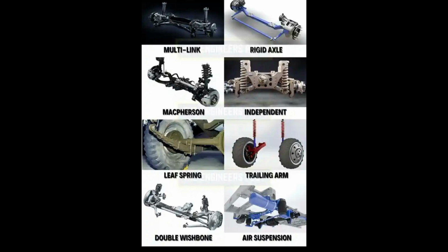Multi-link is a type of suspension that has quality grip, and with this suspension, controlling the car becomes easier. The multi-link suspension also has many variations. If this suspension is damaged, then the replacement process takes a long time and the spare parts are still rare, so the price is relatively more expensive than other suspensions.